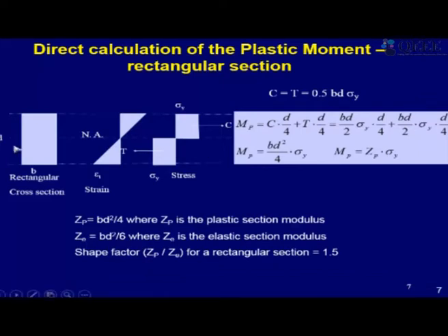So it is actually called the equal area axis. Okay, so that is how we first locate the neutral axis, and then with reference to the neutral axis we locate the CG of that area which is in compression, and we draw the stress resultant C at that CG and draw the stress resultant T at the CG of the lower area. So in this diagram, okay, and then that gives you the lever arm. So that gives you the calculation for Mp.